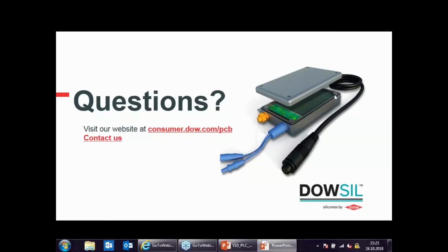So the next question. The question here is if a fully waterproof durable coating exists. Well, let's say it in this way. Silicone conformal coatings are waterproof in a way. So if you talk about water, they are waterproof. So you can put water on them. There's not an issue. It will not go through.